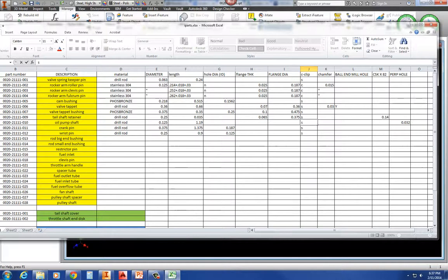Yes. Okay, so what we were saying is that the length of the shaft, the distance of that C-clip undercut on page 8 of every one of those bottom 3 parts is the same distance from the end. So it's essentially the length of that changes. So I have in my links for these, 0.214 plus 18 thousandths plus 0.03. So that's the entire length without the flange. So then the flange is going to add more length to that. That's the way that I set mine up.